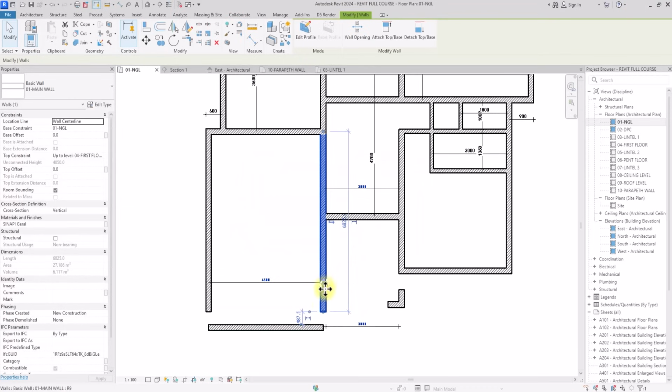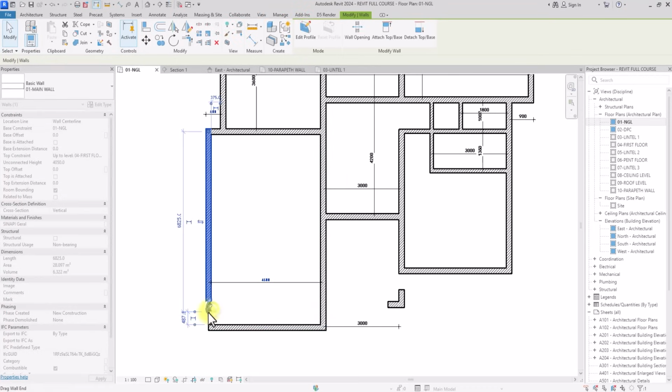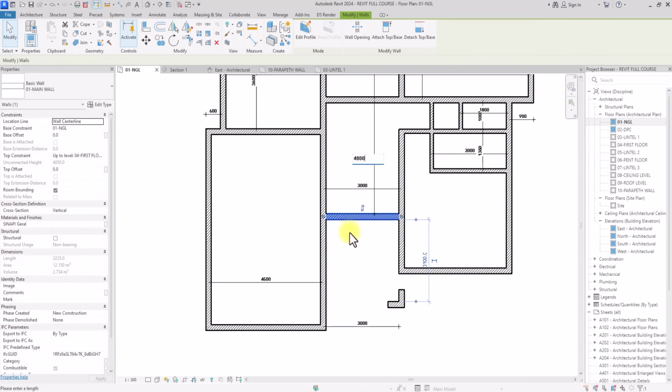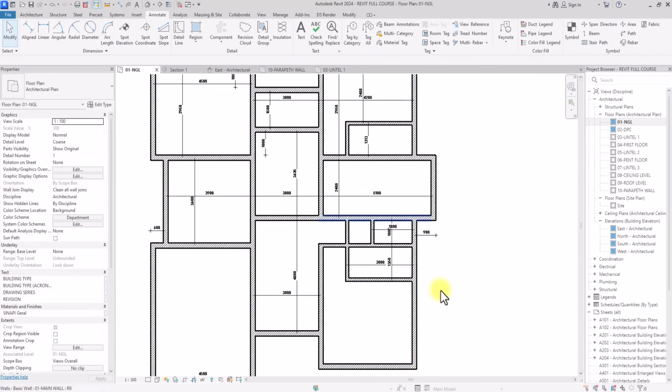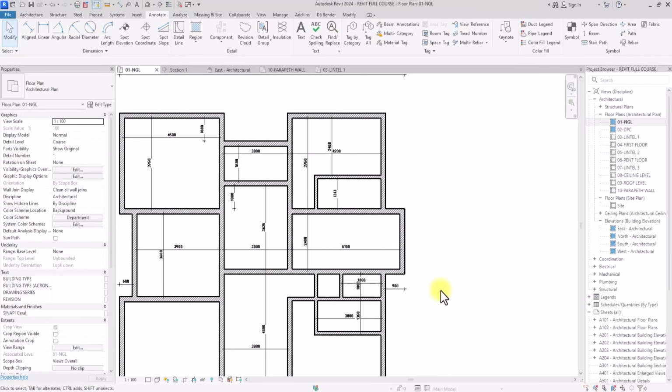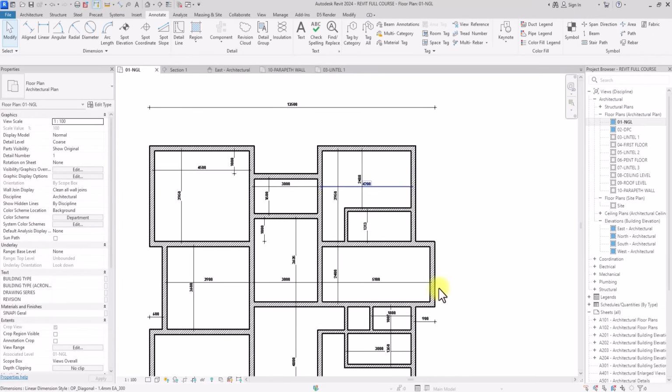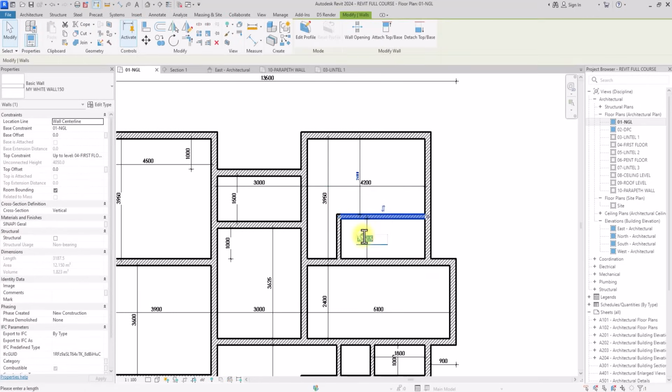Going to delete this. I'm just going to align this to this. Regardless, I'm also going to click this and extend this to, let's say, 4.8, this foyer. So I extended everything by 600 millimeters, so it will be more balanced. So I'm going to check out this region too at the back. This place is actually very tight, so I'm just going to adjust this bedroom as well.